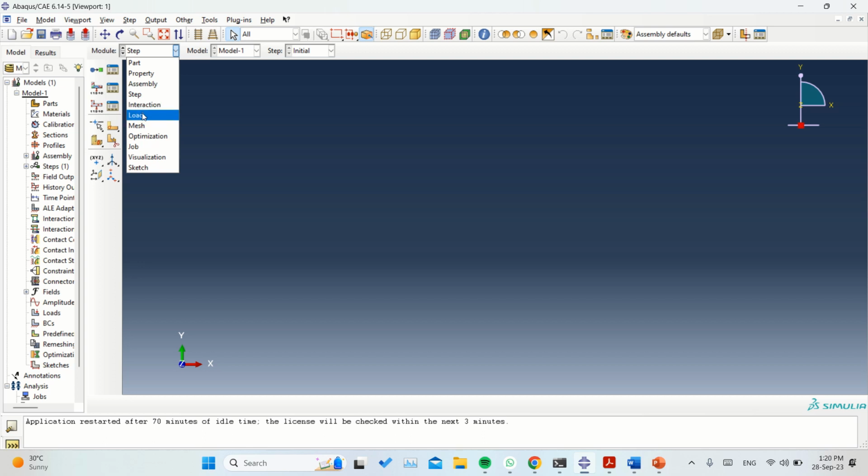Load. Just apply the load. At which location should you apply the load? That is the loading condition. You will select the location and apply the load there. In your case, the column, of course, you will apply the load on the top side of the column. The bottom side will be hinged, maybe fixed. All the boundary conditions will be defined here. Boundary conditions involve support conditions and loading conditions. All will be defined here.